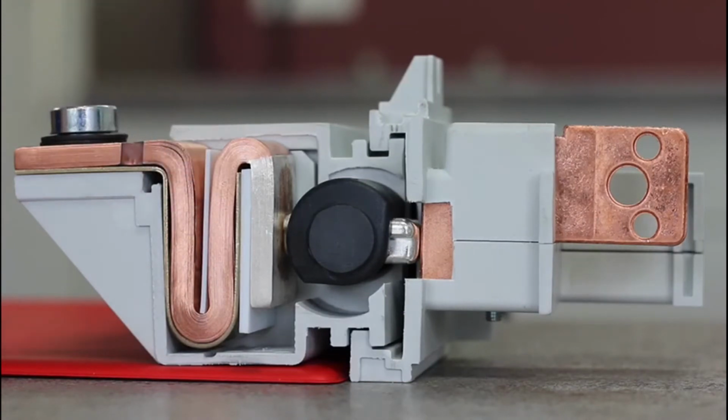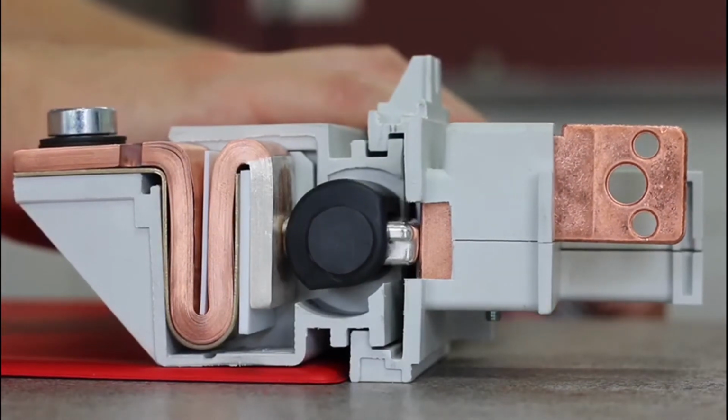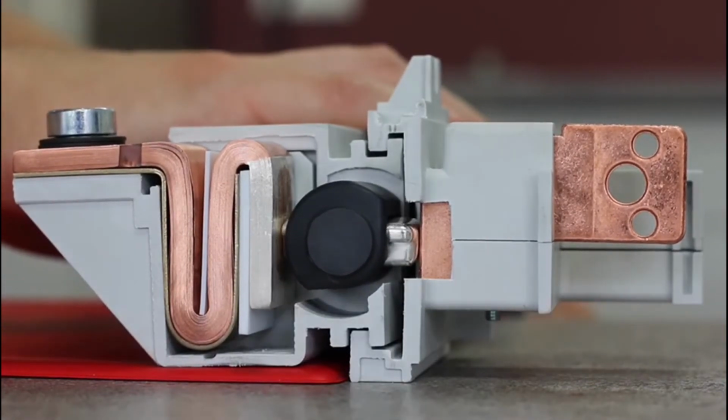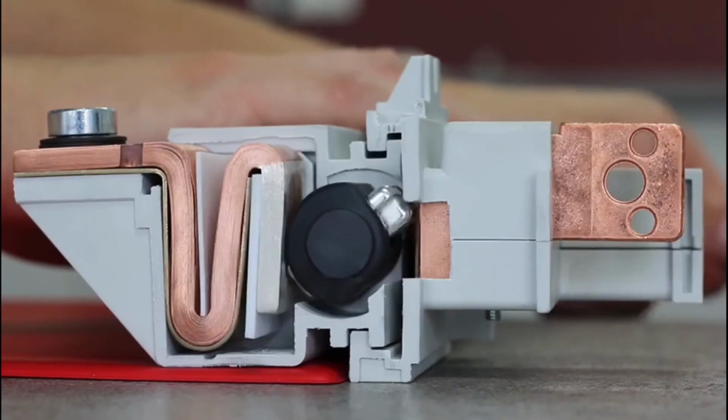The anti-parallel flow of the current through the U-shaped copper layer reinforces the contact pressure in case of a short circuit caused by the electromagnetic field generated within the U-shape. By turning the operating key by 10 to 15 degrees to left and right and doing this several times, the contacting bolt starts to rotate axially. It is realized in this way to break up a small welding point, which might be caused by an overload, before the bolt is turned back to disconnected position.